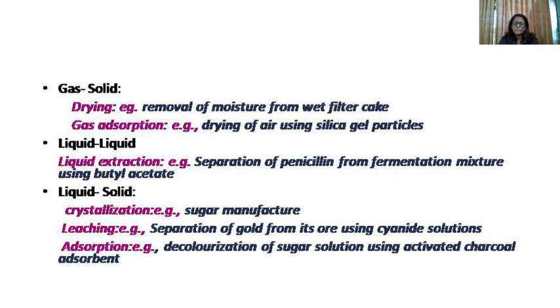Okay, if you want the filter cake in dry form, we can keep it in drying equipment and contact it with a stream of dry hot gas, which heats up the material, thereby the moisture gets evaporated, and that vaporized moisture is removed by the same drying gas, which is called the drying medium. So this is an important application of drying operation.